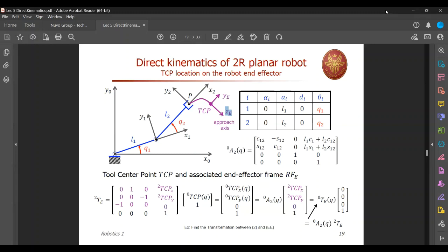So these are the things definitely you need in robotics, right? You should be able to look at two coordinate frames and figure out how the first frame has rotated in order to coincide with the second frame, right? Because you have three axes, just three options, right? You figure out whether it is x-axis, y-axis, z-axis, or by how much.